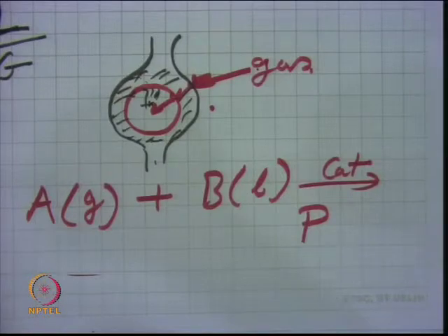So, in this case the liquid flow rate is roughly 10 to 30 meter cube per meter square per hour, which is what you call the mass velocity. One can also define it in terms of the superficial gas velocity. So, Ug divided by UL, the superficial gas velocity over the superficial liquid velocity, which is based on the tower diameter.